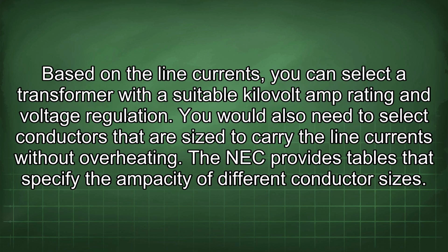Based on the line currents, you can select a transformer with a suitable kilovolt-amp rating and voltage regulation. You would also need to select conductors that are sized to carry the line current without overheating. The NEC provides tables that specify the ampacity of different conductor sizes.